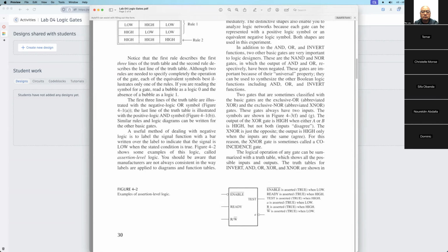So last time we used the decoder, the BCD code decoder, right? So we used this before. For the pin with the circle and the overbar here, this means this pin will get true when the input is low. So the input is low, after negation it's high inside, so the variable is true.